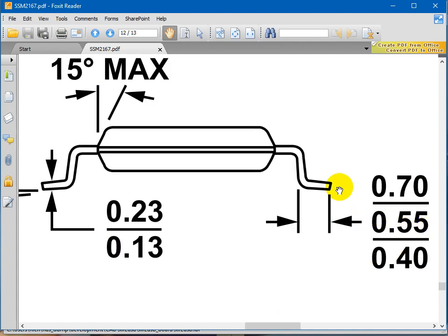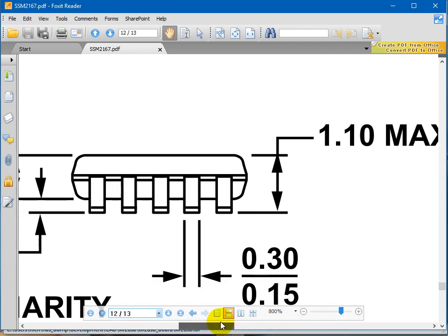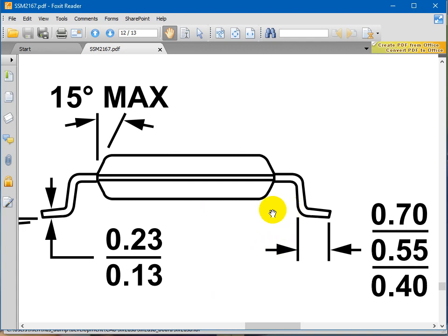What happens with solder is you put down a copper pad, and then you put down paste on top of it, and the reflow process will kind of wick it up, sort of like this. Okay? And I want that reflow wicking up to happen mostly in this direction and not so much over here. If I have too much wicking over here, I lose my clearance between two pads, and I don't want that. But in this direction, I've got all sorts of space. I've got parts underneath and anything that goes off the edge.